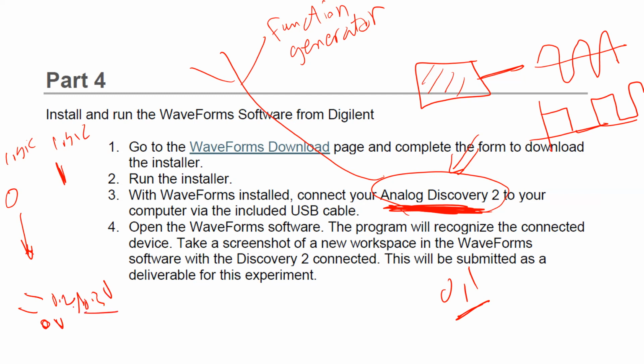You can get the exact number from the chip, since every chip may be a little different. Any voltage very close to 0 is taken as logic 0. Logic 1 is usually around 5 volts, with a certain range, maybe 4.5 to 5.